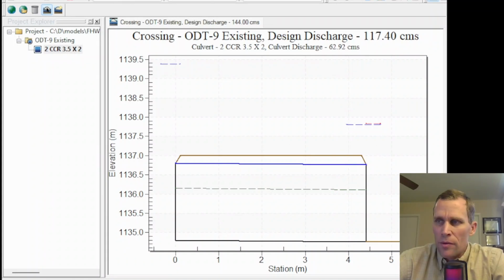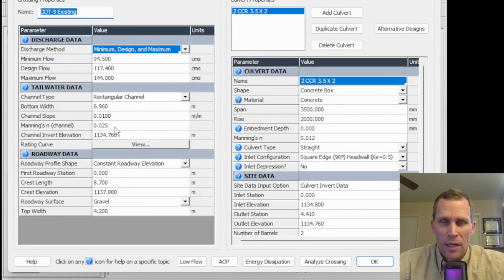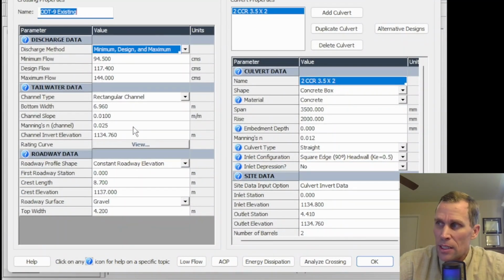From the PDF report that Elias sent me, translated into English, there was a paragraph that concluded what we've already learned from the existing culvert situation and the analysis, and it reads, the results of the profile and cross-section indicate that the water depth exceeded the height of the box type section, even rising above the roadway elevation. Therefore, the structure must be replaced with one that meets the design flow and road design requirements.